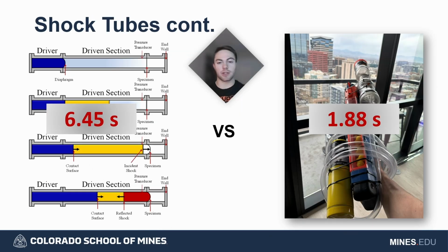So I did that calculation, and then I measured in real time what actually happened during the videos that I took. So again, for our laminar approximation, using that code, we got a time of 6.45 seconds, which is very much on par with a propane-like, methane-like gas going at an equivalence ratio of 1 and a high speed through the tube. And then in the second figure here, I got 1.88 seconds for my demonstration, which is like 3 times faster. So why is this?